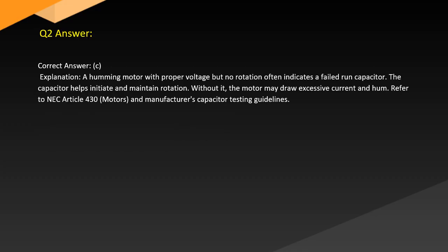Answer. Correct answer, C. Explanation. A humming motor with proper voltage but no rotation often indicates a failed run capacitor. The capacitor helps initiate and maintain rotation. Without it, the motor may draw excessive current. Refer to NEC Article 430, Motors, and manufacturer's capacitor testing guidelines.